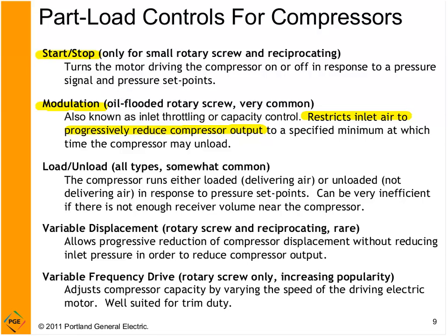Load, unload. Load-unload is kind of a variant of start-stop, except instead of stopping the compressor when we reach another point, we unload the compressor. What it means to unload the compressor is the oil sump is allowed to blow down, so the compressor is no longer fighting against full system pressure. Incidentally, with modulation, you are fighting against full system pressure. It does not blow down.